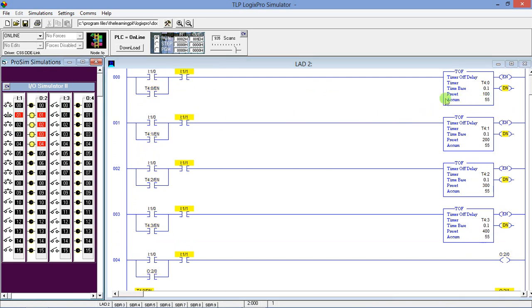When the first timer starts, the accumulator value comes to its reset. The second LED stops. After 20 seconds, the third LED will stop, after 30 seconds this LED will stop, and after 40 seconds this LED will stop. This is all for the function. So this is all for the off-delay timer and this exercise.